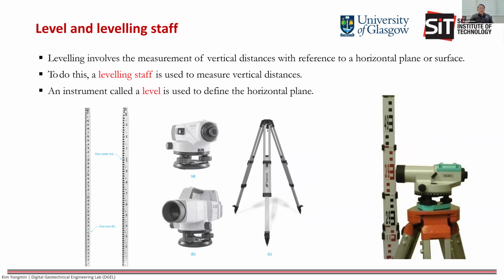So, level and leveling staff. These measure vertical differences. One is the optics, and the other is a staff. You use the level and the staff to measure things like drain gradients, to reduce levels. This is a very basic skill, and we'll be covering it in our first lab session. Precision leveling ensures things like water gradient flowing well, and it can help to prevent future ponding issues after construction.